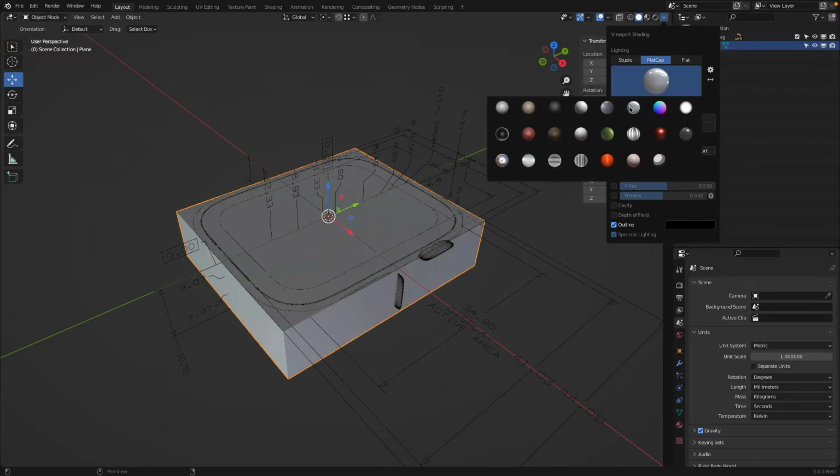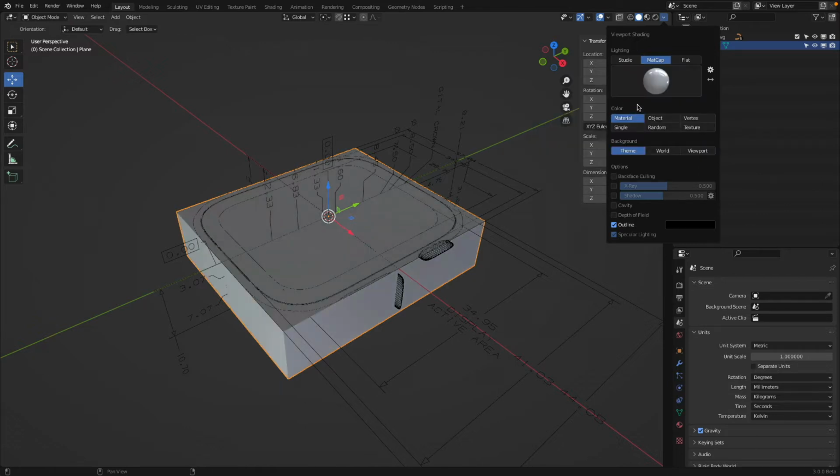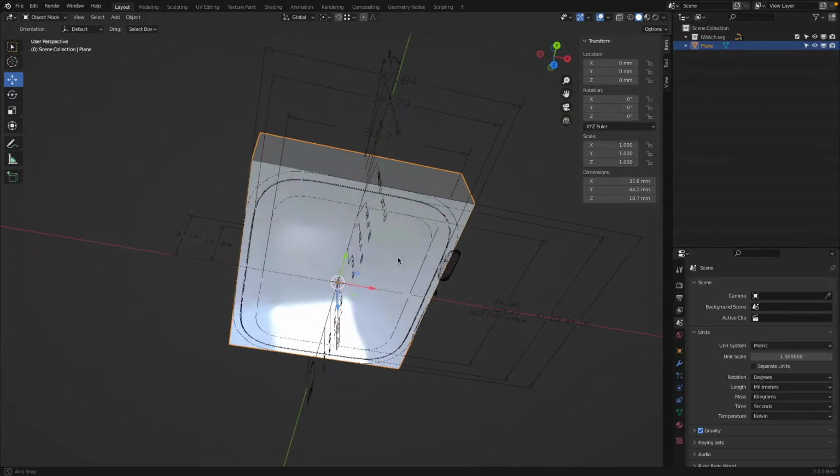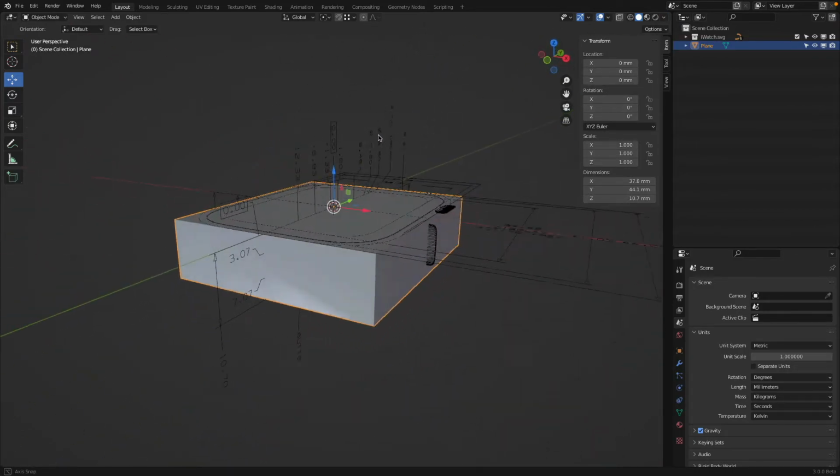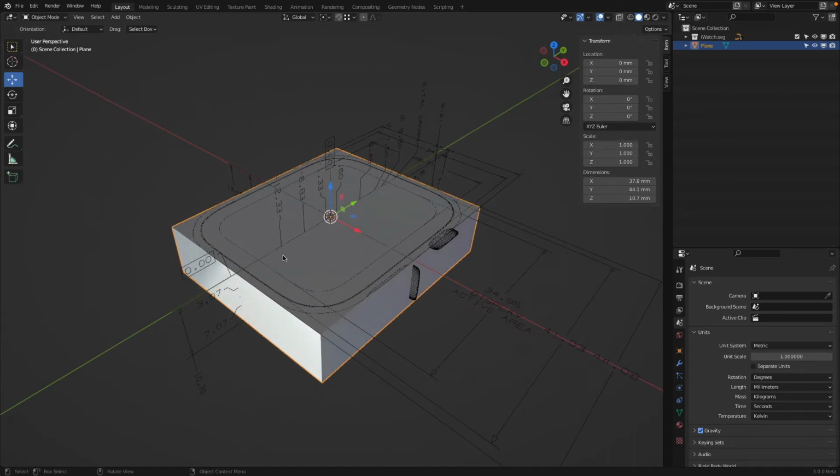They are quite useful, like reflective materials and so forth. So I will go here to this type of matte material. It's very similar to the one we have in Alias for studying the highlights on it. You see the highlights on it, and it's very useful when we create organic surfaces to check how the highlights change over a surface.